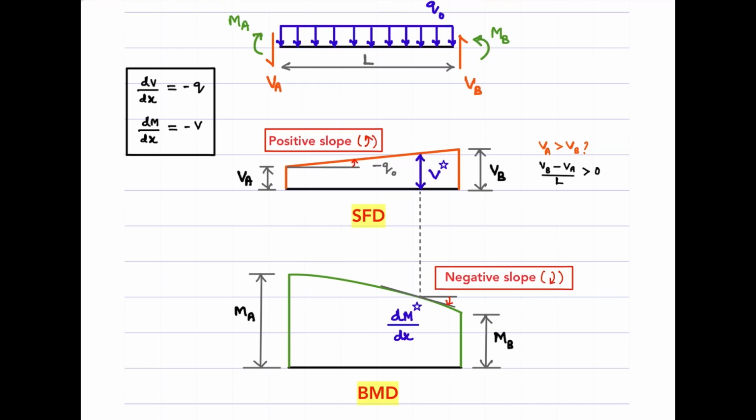Now the question is how we want to connect these two ends. Should it be with a straight line? What's the problem with a straight line? If I have a straight line, the slope of a straight line is a constant, which means the shear force diagram will have a constant ordinate throughout, right? So if you have a straight line, that means the shear force diagram should be something like this with constant ordinate everywhere. But here I have a shear force diagram with its ordinate constantly increasing, right? Which means I should have a curved line here.